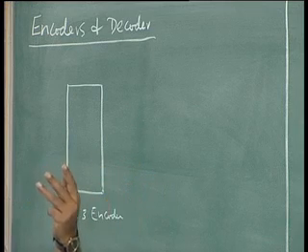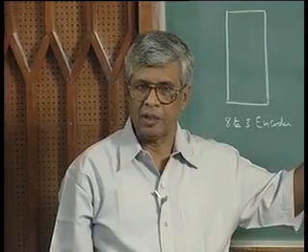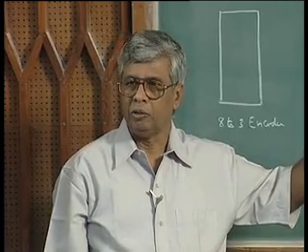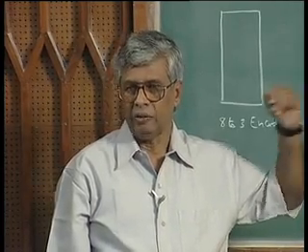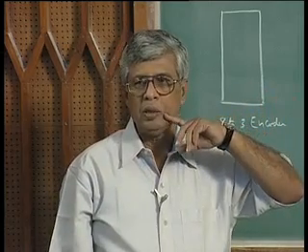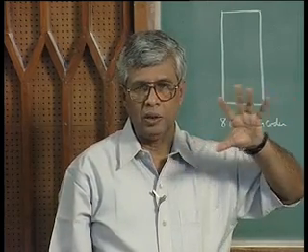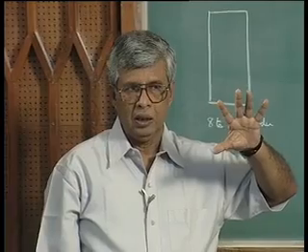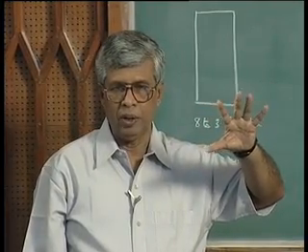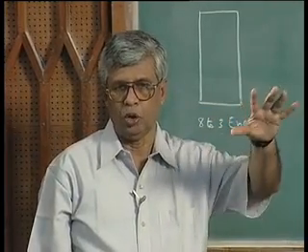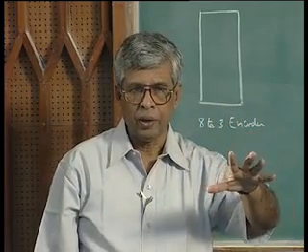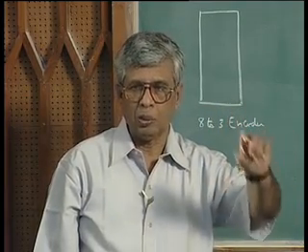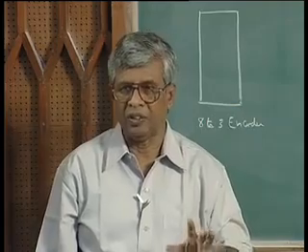So, you need only 3 bits for that. By combination of these 3 bits we can determine which is the active input, all others are inactive at that given time. So, this is the process of encoding. Encoding reduces the number of inputs required from 8 to 3 for example, or 16 to 4. So, compressing the data from different possibilities into a smaller number of bits, that is the process of encoding.